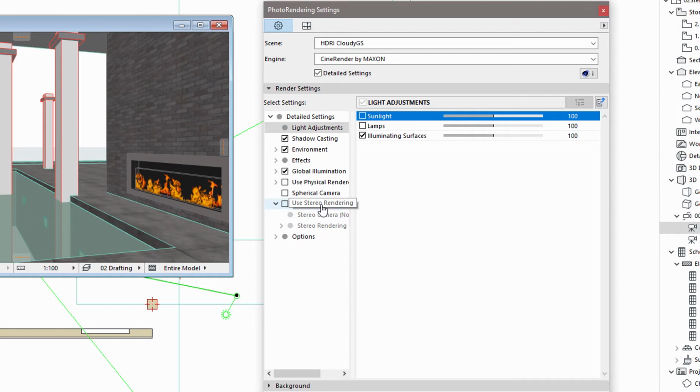Please remember, if this panel is not enabled, the resulting rendering will be two-dimensional. But, as long as this panel is enabled, all created renderings will be stereoscopic. For stereoscopic results, every image must be rendered twice, a slightly different image for the two eyes. This means that 3D renderings take twice as much time as conventional 2D renderings.